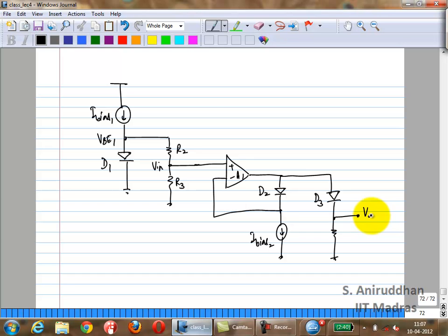So first of all, what is Vn? Vn is nothing but VBE1 times R3 over R2 plus R3, correct? I'll just call this VBE1 over K. What is VO?